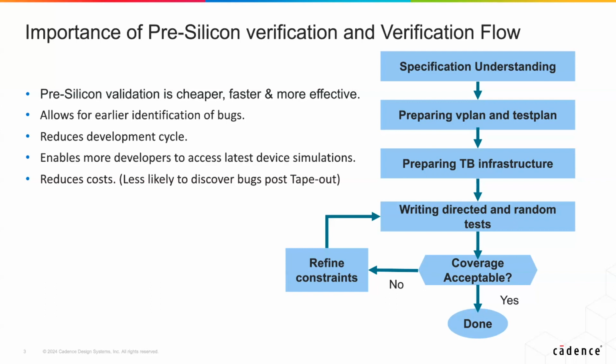Now, how would we go about verification? As one would say, a 1,000 miles journey begins with a step. The first step in verification is reading the specification and understanding it. After reading the specification, we need to formulate an attack plan. We create our plan by checking the IP specification, the rules, the various request types, what kind of illegal scenarios or what kind of coverage points we need to target.